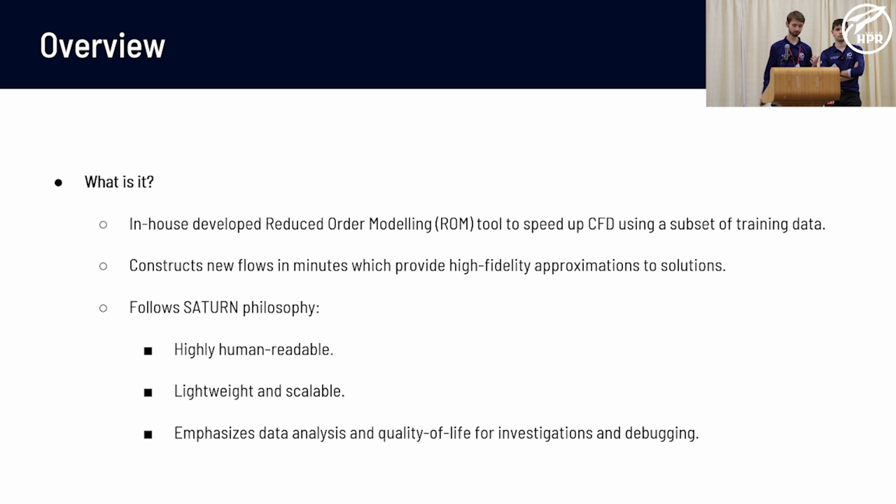Well, what we do is we take a small amount of points in our aerodynamic database as training data, and we ask Fluent to solve them normally, and then using this smaller set of training data, we pass it into Andromeda. Andromeda then looks at these CFD flows and deconstructs the data, and it tries to find underlying correlations between these flows and creates a meta model. And then using this meta model, we can then reconstruct the remaining fluid flows in only a few minutes, which are then passed back into ANSYS Fluent, which just derives the drag from the flow solutions, and we get our full database.